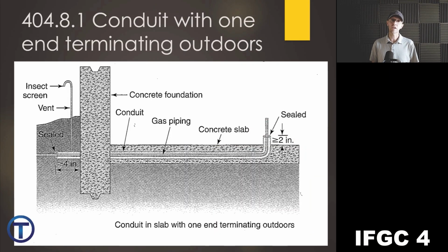We can see how careful we are about putting gas pipe below ground. Now, why is that? Why is it a problem if you have a gas leak below ground? Natural gas is lighter than air, and it's going to try and come up into the building. And if there's a leak below ground, it's going to be really, really hard to correct that problem. Because how do you even find it? And once you do, we're pretty invasive by the time we get that leak fixed. So, putting it in a channel is one way, but that's not to say you can't bury it.